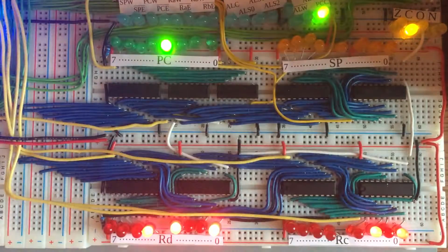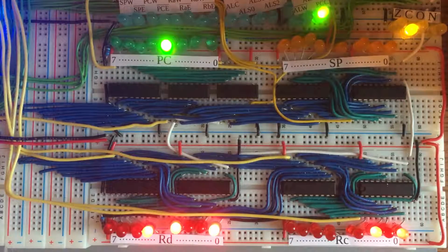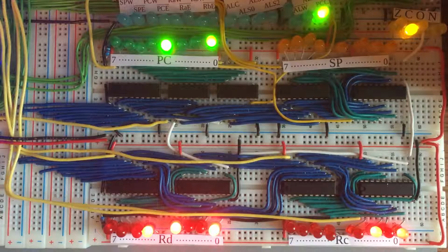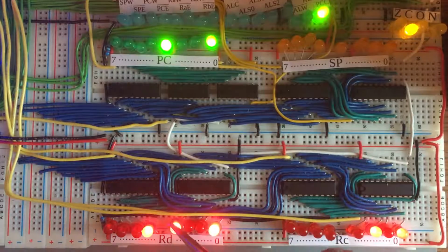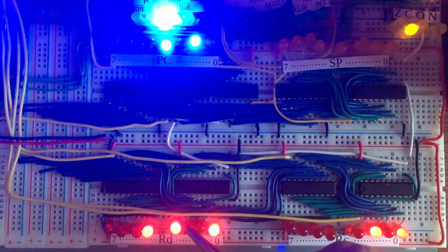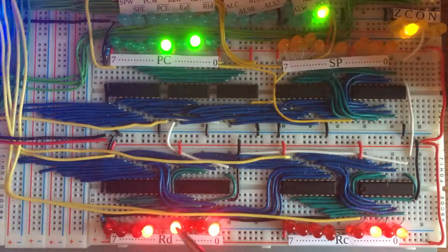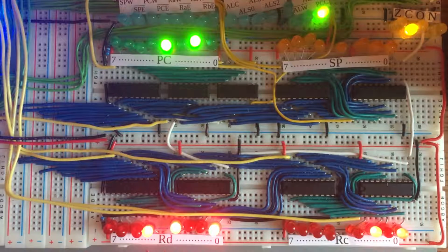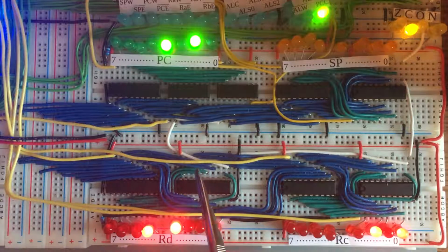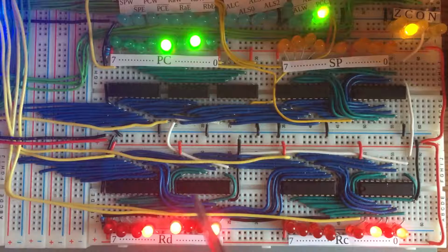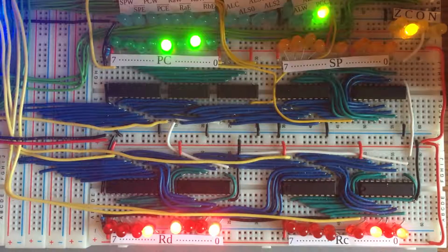So for example, in this case, you can't see it right now, but there's some totally different value on the bus. And even though I advance the clock, nothing's happening with the D register until that enable line gets enabled. And of course, that's not the case right now. So this value is just going to stay there until we actually instruct the D register to take in a new value from these blue wires. And as long as it's not doing that, it's going to keep whatever value is stored in there.